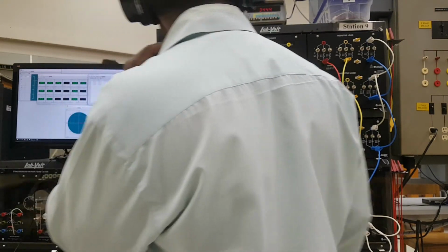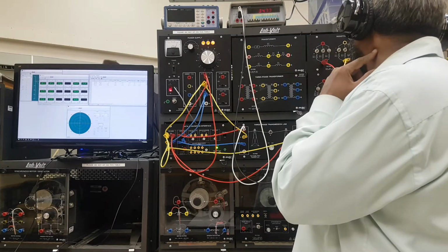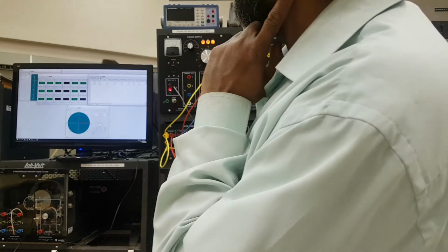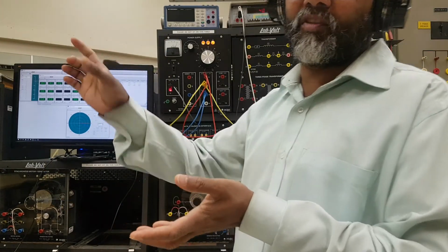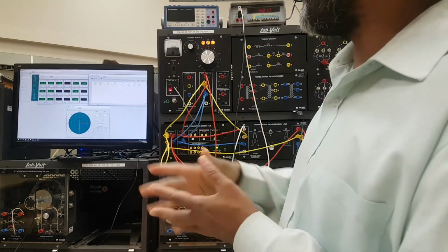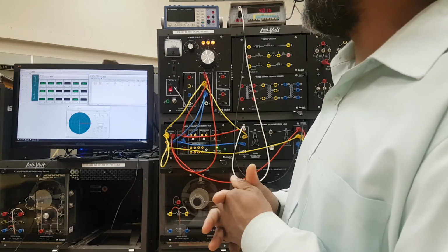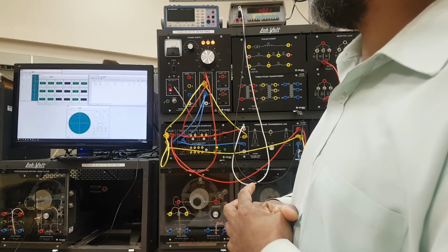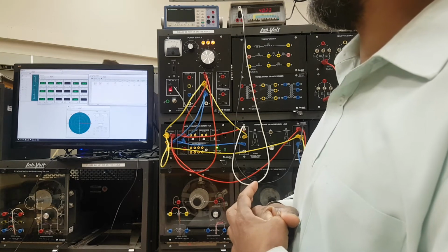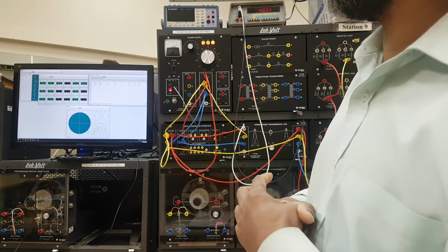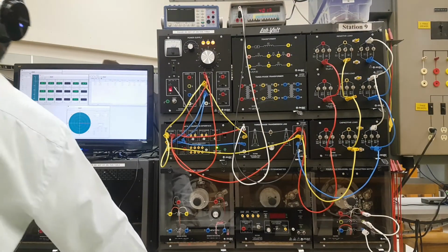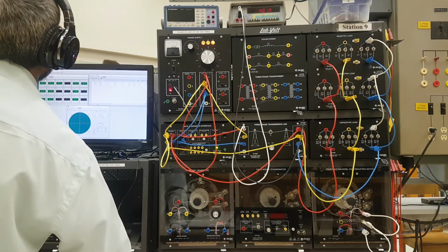So that means I think by adding this one we are getting a little bit of over voltage, but the difference between the sending and receiving voltage is minimum in this case. So 207, 208, 14, there is a 6 volts difference there. In that other case it's more than 6 volts. So we'll take this one.